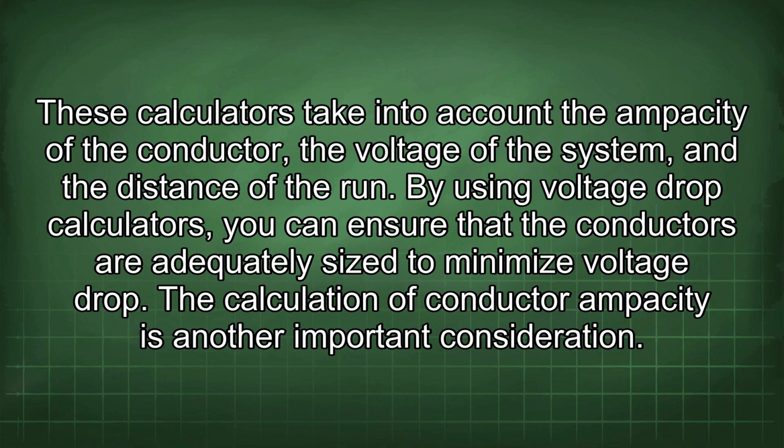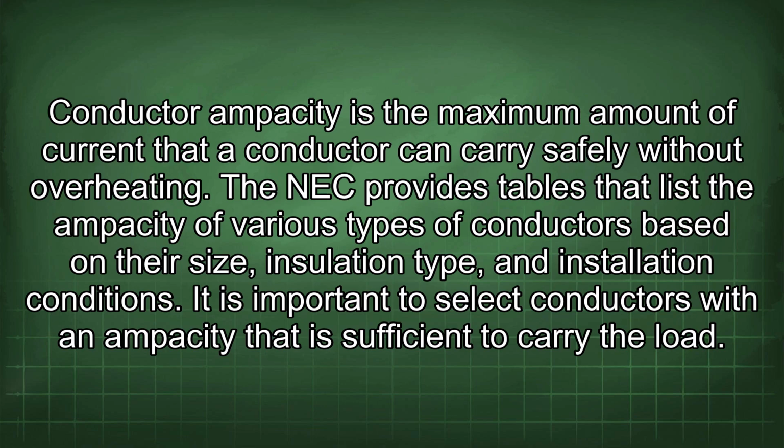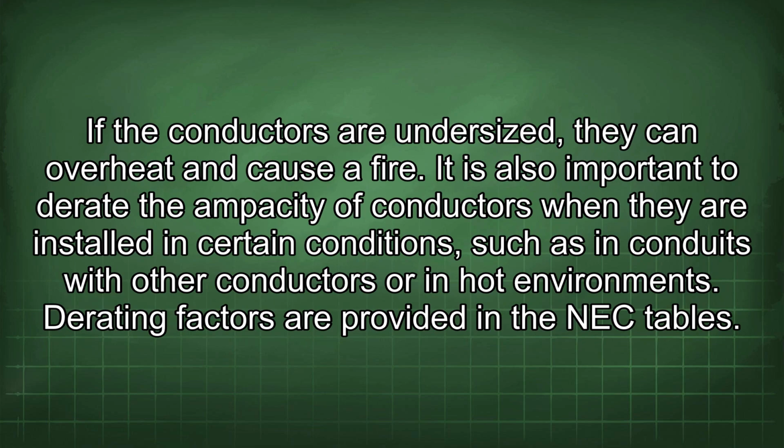The calculation of conductor ampacity is another important consideration. Conductor ampacity is the maximum amount of current that a conductor can carry safely without overheating. The NEC provides tables that list the ampacity of various types of conductors based on their size, insulation type, and installation conditions. It is important to select conductors with an ampacity that is sufficient to carry the load. If the conductors are undersized, they can overheat and cause a fire.